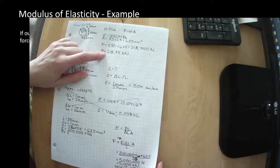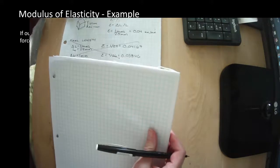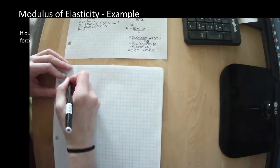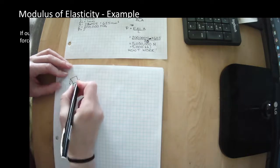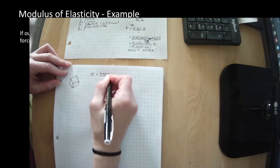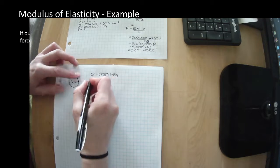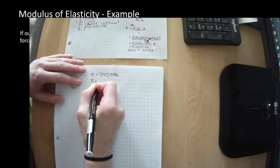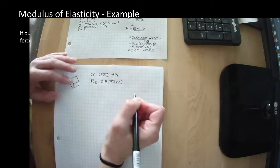I wonder how much would it move with the 218 kilonewtons on it. Let's see what that would be. So we have our cube, and we know that the stress max is 350 MPa, and we figured out the area. So we know that this directly relates to a maximum force of 218.75 kilonewtons.